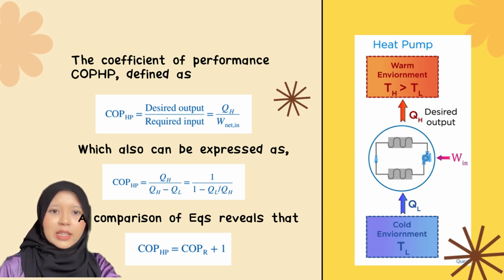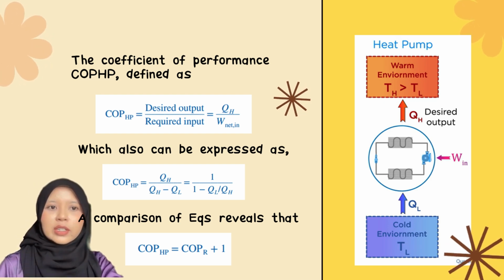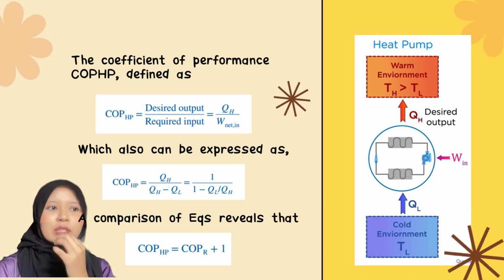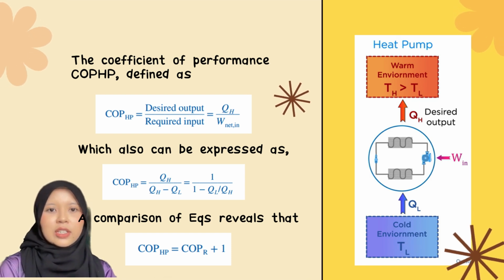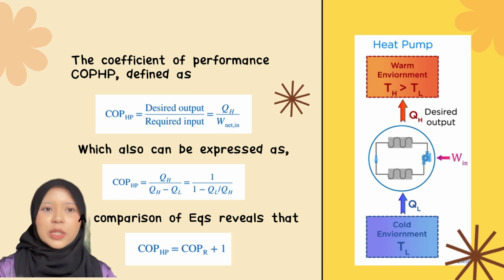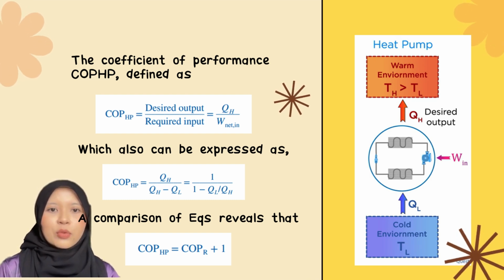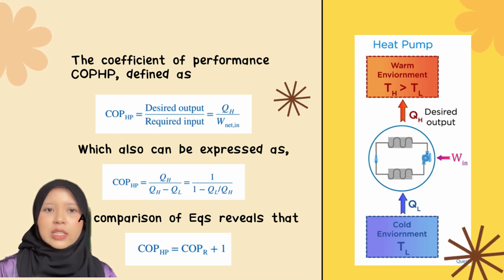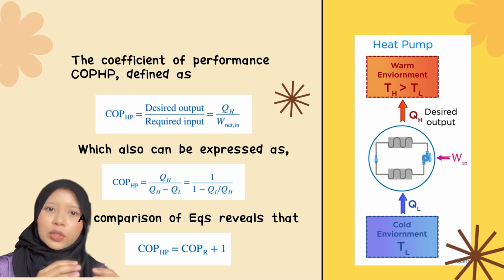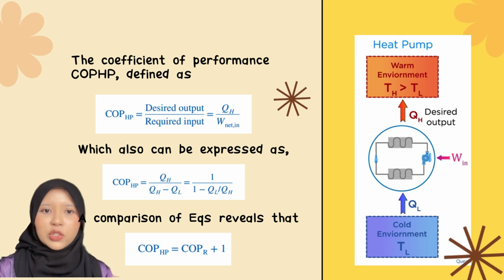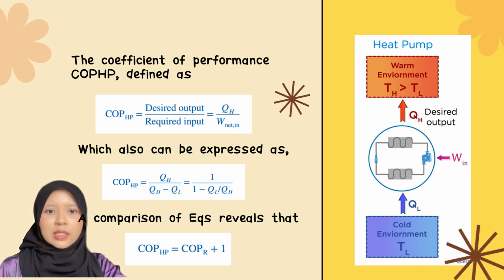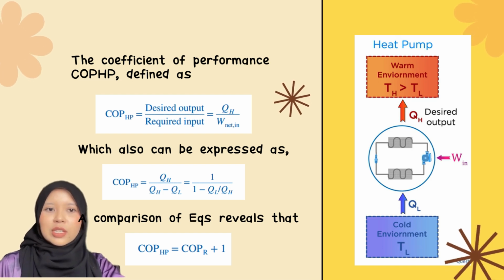This implies that the COP of a heat pump is always greater than 1 under ideal conditions. So the efficiency under ideal conditions is a COP that can range between 2 and 3 seasonally, where energy loss occurs as some QH is lost to the outside air, reducing efficiency. In cold climates, the COP may drop below 1 when outside temperatures are extremely low, and the system switches to resistance heating mode in such cases.